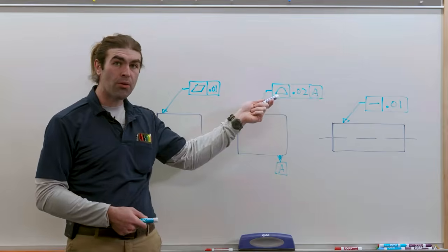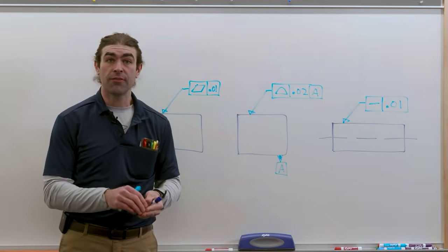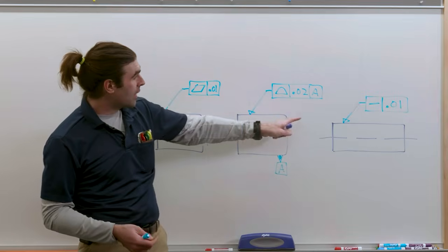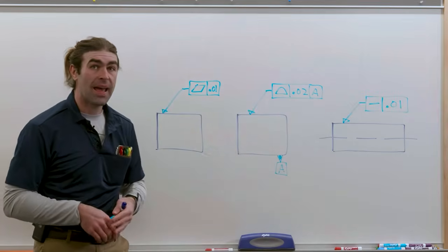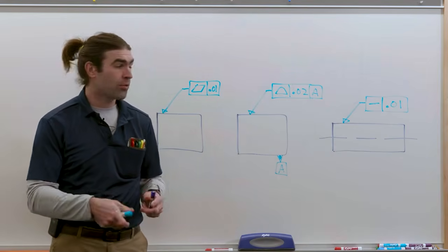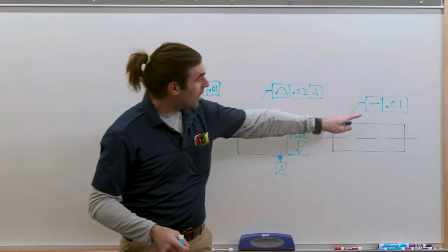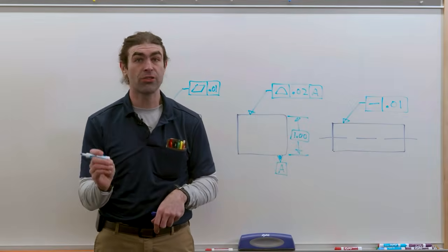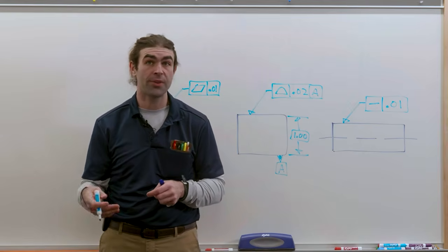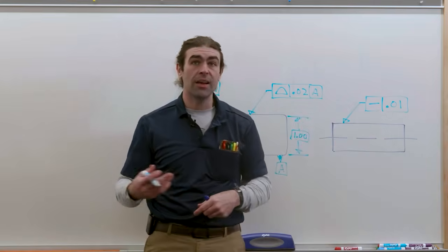Next up, we've got a profile, which is very tricky. Profile can do a lot of different things. It can function just like flatness, or it can locate surfaces. In this case, with a datum reference to datum A, it's doing the job of flatness, parallelism, and locating a surface if we have a basic dimension. And then another form tolerance, straightness, applied to the surface of a cylinder. This controls the line elements around the cylinder. Very simple feature control frame, just the symbol and then a tolerance.